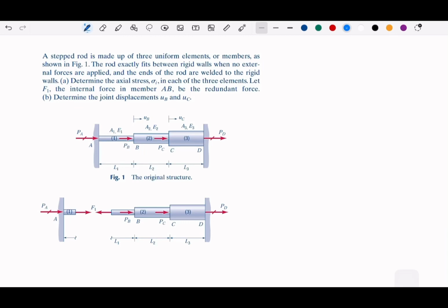We haven't discussed much yet about this part. So this is still in the axial deformations, the statically indeterminate structure. Sometimes you have, suppose, some structure that is attached at both ends to the wall, and there are some elongations in between, but since we have walls attached to the structure, the total elongation we assume will be zero.